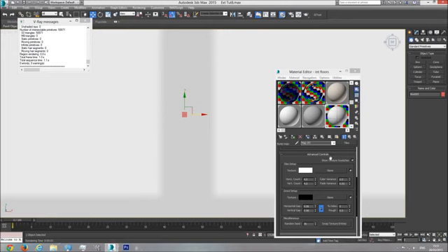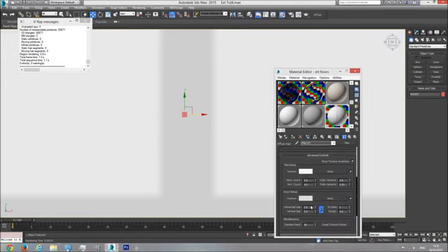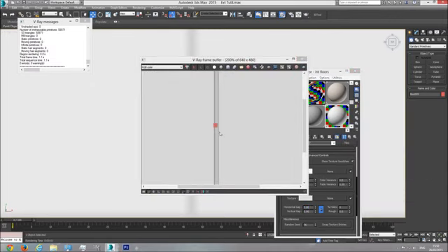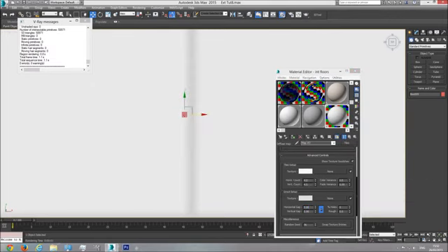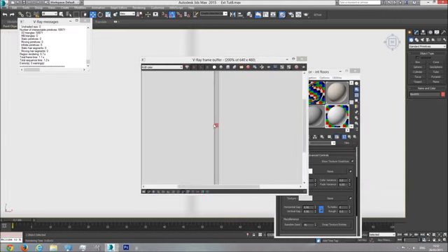Something strange happened here. Let's go to tiles. Oh, I by mistake did 0.6. It needs to be 0.06. Okay, so like this. Let's render it. Okay, separation is about right. So it's about half a centimeter.